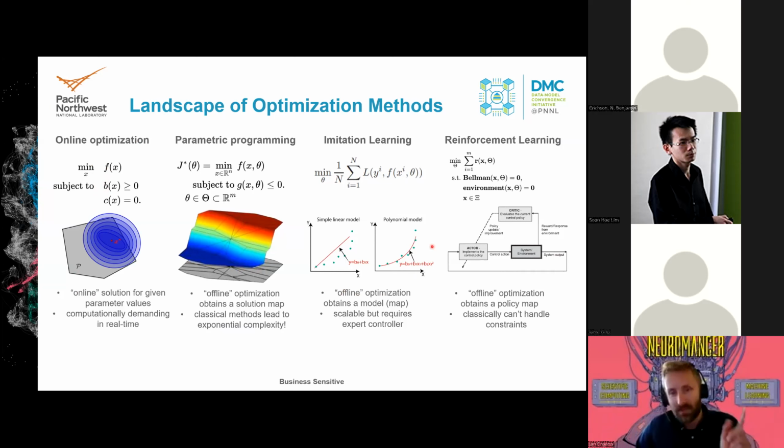Okay, how do we alleviate the first problem of requiring an accurate system dynamics model? Well, we can do reinforcement learning when we have some system that can be a real physical system or computational, and we just observe the response to the perturbation of the control action, that can be reward, and the next state. We train the critic, which can be approximated by a black box neural network, take the gradients of it to obtain the policy gradients for the actor, again, a neural network. This needs to satisfy the Bellman equation, and there is a lot of research on doing reinforcement learning that is, again, offline optimization that will give you an explicit control policy that solves the optimal control problem without requiring any assumption of your system dynamics model. Unfortunately, very often it's difficult to satisfy constraints and stability requirements when you don't have the prior knowledge.